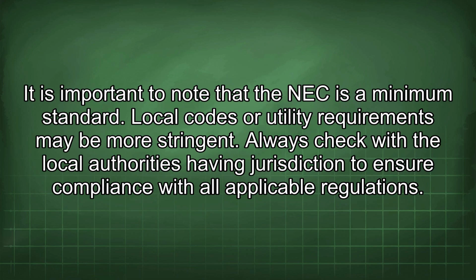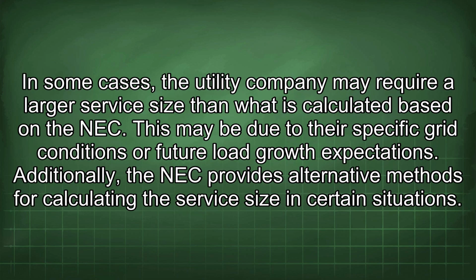It is important to note that the NEC is a minimum standard. Local codes or utility requirements may be more stringent. Always check with the local authorities having jurisdiction to ensure compliance with all applicable regulations. In some cases, the utility company may require a larger service size than what is calculated based on the NEC. This may be due to their specific grid conditions or future load growth expectations.